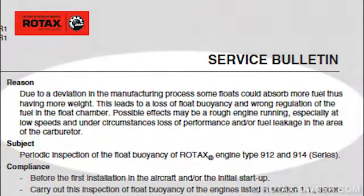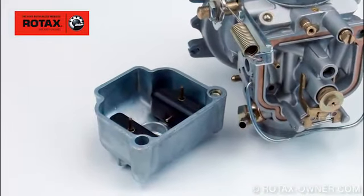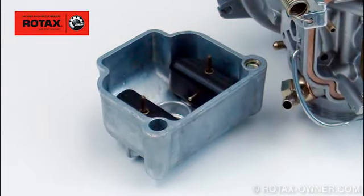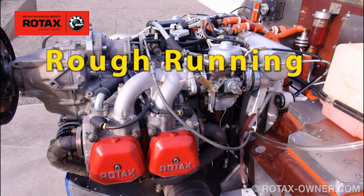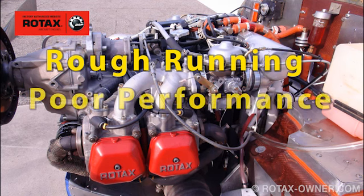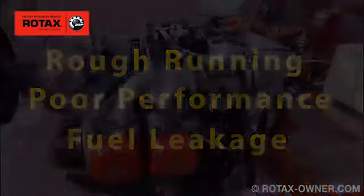Due to a deviation in the manufacturing process, some floats could absorb fuel and so have more weight than others. This leads to a loss of float buoyancy and improper regulation of the fuel in the float chamber. This may result in rough engine running, especially at low speeds, loss of performance, and/or fuel leakage in the area of the carburetor.